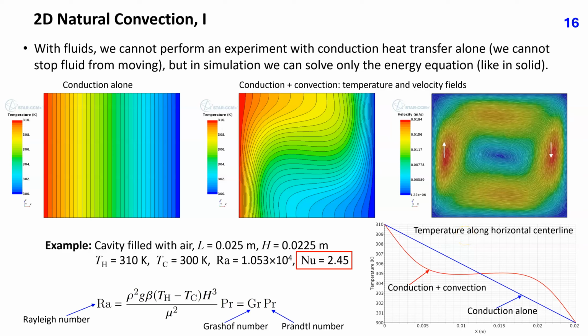With fluids, we cannot perform an experiment with conduction heat transfer alone because we cannot stop fluid from moving, and as soon as the fluid is in motion, convection is involved. However, in simulation, we can solve only the energy equation in a fluid domain, like in solid.